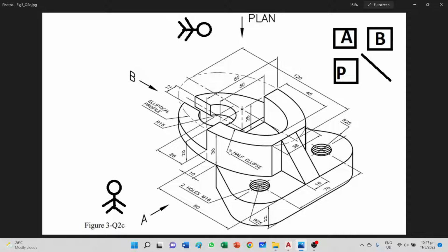Okay, so when you study this diagram closely, you will find that the plan view offers the most amount of dimensions in which you can complete the geometries. So you will naturally want to begin with the plan view for this particular case. There are some cases where the front view presents more dimensions and it's easier for you. So I'm going to start off with the plan view, and the plan view is at the bottom right hand corner.